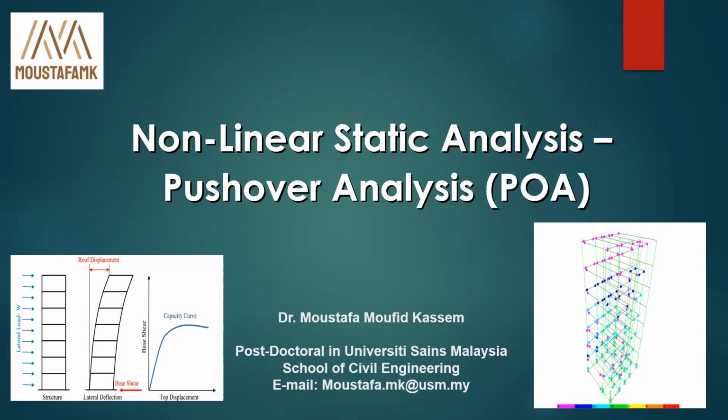Also, the pushover analysis, as you know, is a static method which helps to simplify the nonlinear technique to estimate the seismic structural deformation, the structural performance, and the seismic behavior of the structure under seismic loading and lateral loading using a static method. This static method is different from the dynamic method.